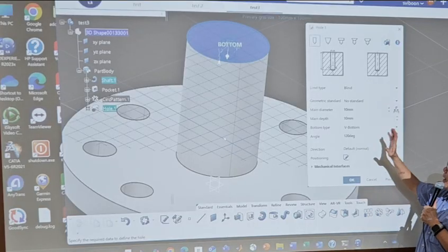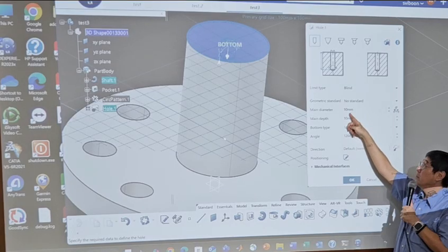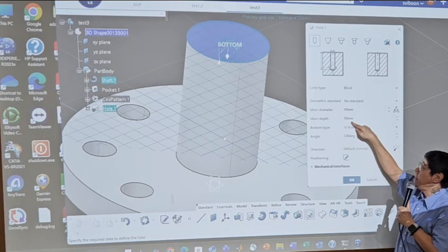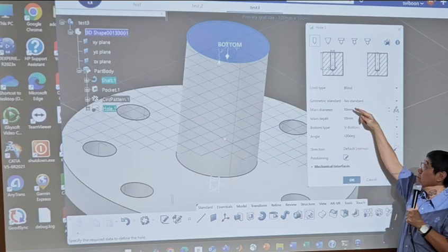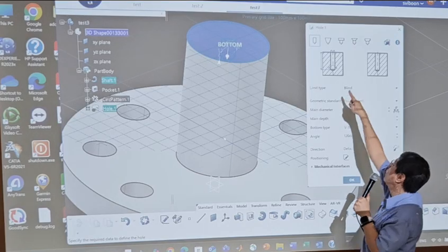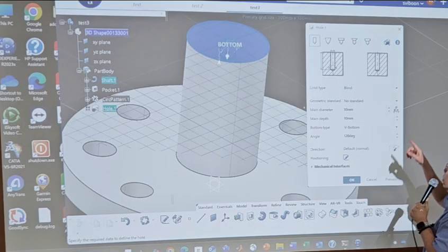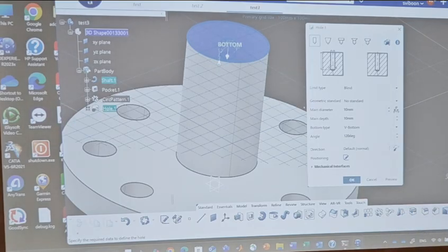Now you look at this one, you have main diameter, right? You have main diameter here, main depth here. Right? Main diameter, main depth. Look at this hole over there. You see, this we call a simple hole. Main diameter, main depth. Look at this one, you see? Diameter and depth. You can also have a V shape here as well.